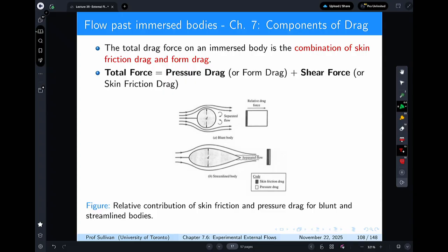And the relative drag force becomes much lower, but the skin friction component, you can see in terms of the little boxes, one on top of each other, the shaded area is the skin friction drag, the unshaded area is the pressure drag. And the pressure drag is very high in the laminar case, but the skin friction is relatively low. But when you go to turbulent flow, you don't really change too much in skin friction drag in this case.